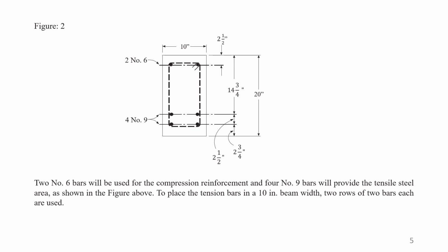For this problem, here is the end of this one, and we will see this figure here. As in the previous problem and previous discussions, we have said that if there is a single layer of rod, the center of that bar in the beam should be 2.5 inches from the outside. In the bottom bar, there are 2 layers.